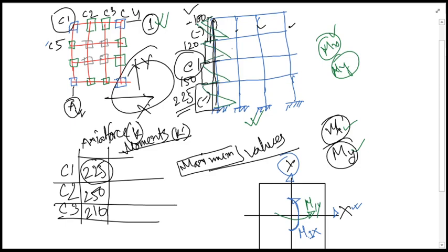Okay, so if this is the pattern of the bending moment diagram, you will be taking the maximum bending moment within this column, say it will be in this portion or in that portion, whichever portion within the C1 column, you will be getting the maximum moment amount.